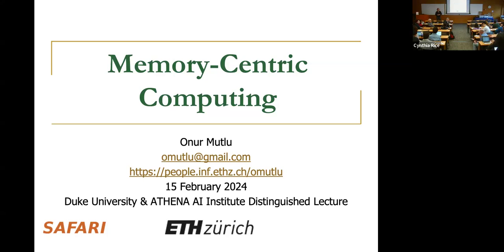Right? So in conventional DRAM, we only need to move the data from the banks to outside the chip because it's processor-centric. But in this case, we need to change the DRAM organization. Yeah, absolutely. Move data inside the chip. Not necessarily the DRAM organization. I mean, we have some works showing that currently there's a bus that connects the banks, but it cannot be used to move data from one bank to another bank. But it can be. There's nothing that limits that really. It's just not possible today in today's DRAM chips. But more advanced versions of this work clearly add better interconnects inside DRAM. And I think we do need that.